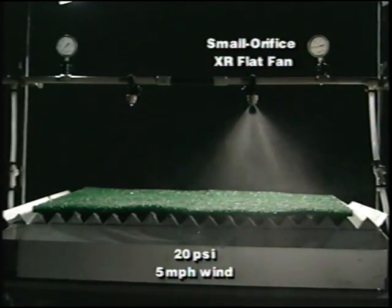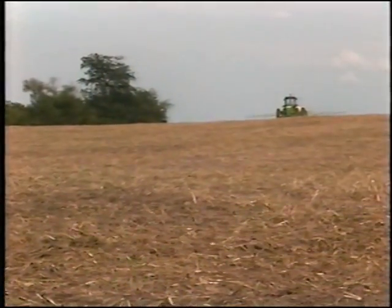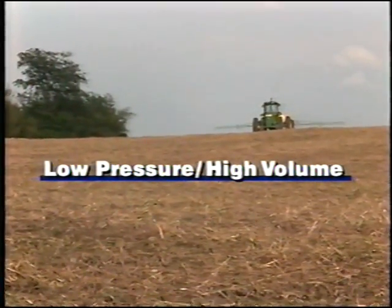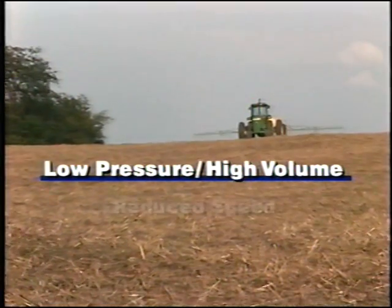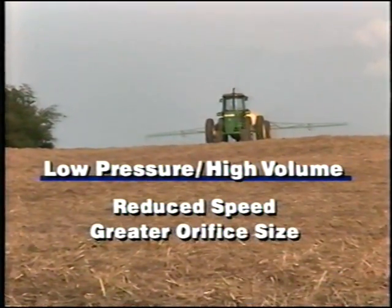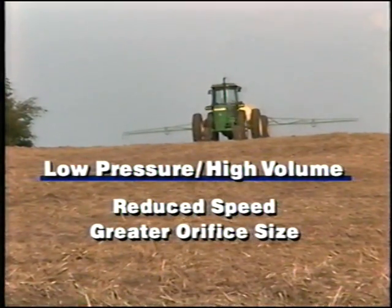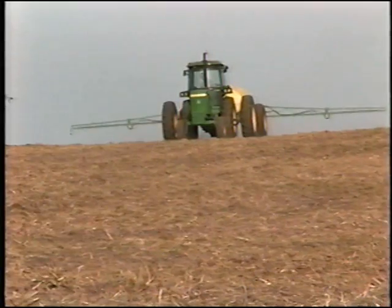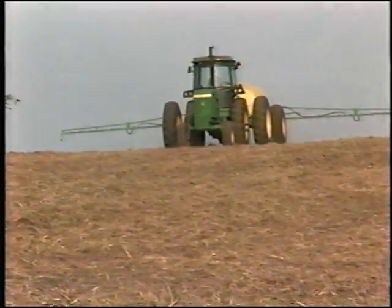Still, for proper coverage at lower spray pressures, applicators must work with higher spray volumes. This can be achieved through a combination of reduced sprayer speed and utilization of nozzles with greater orifice size, allowing larger flow rates per minute, while dramatically reducing the percentage of ultra-fine spray droplets.